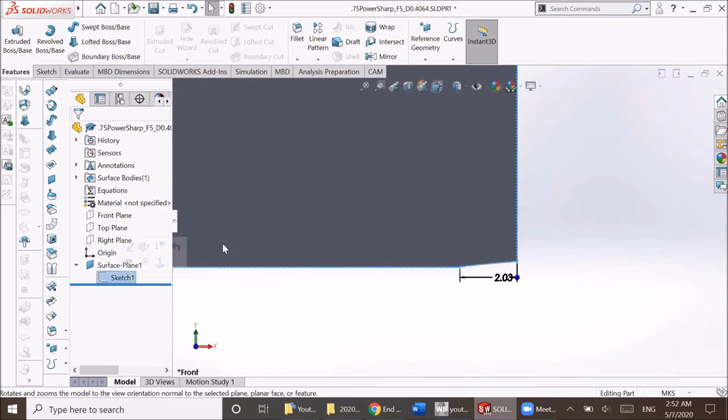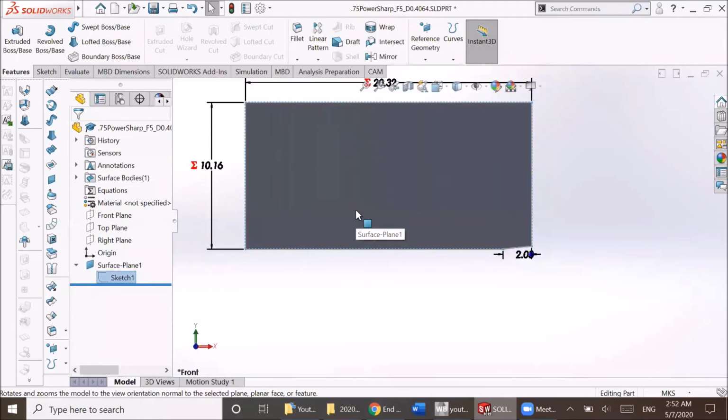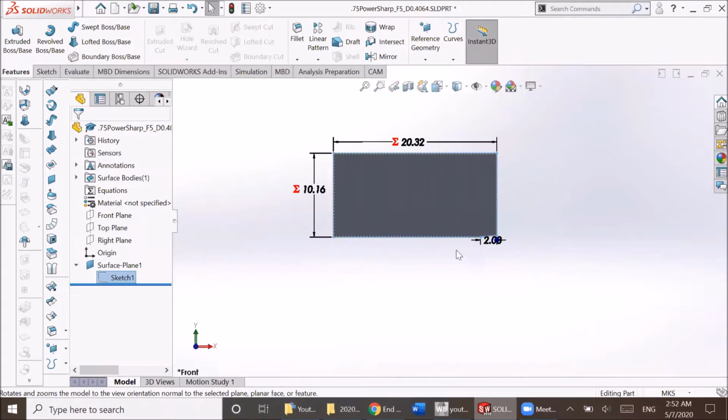So I have just constructed this simple geometry in SolidWorks. And I have made the enclosure or the fluid flow region about 10 times the reference length in the vertical and the upwards region, and about 5 times the reference length in the side region.